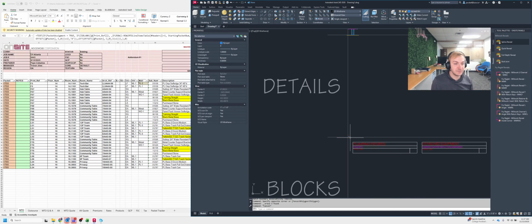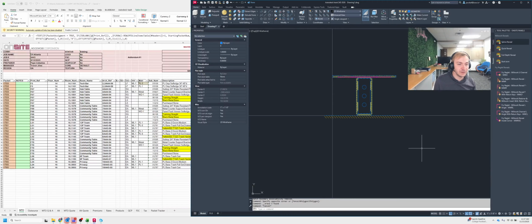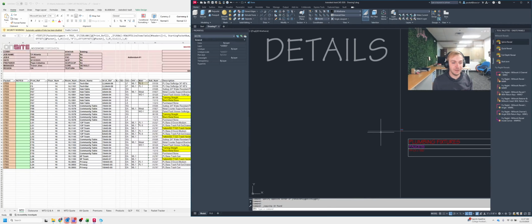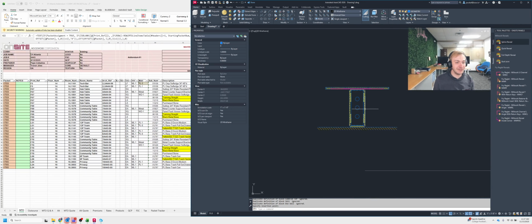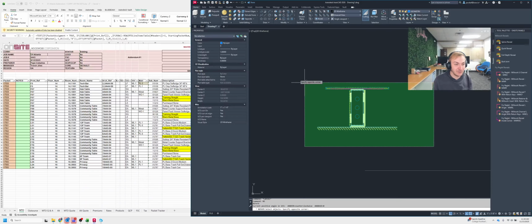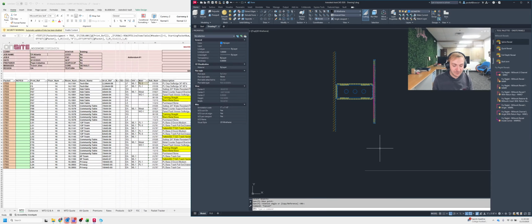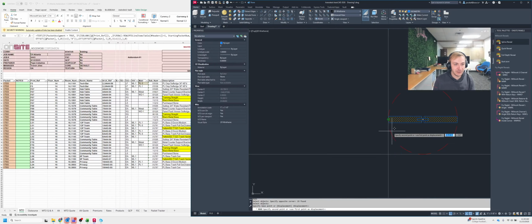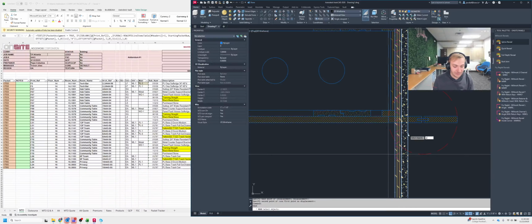So to do that, a good thing you can do is take what you've got from your section view here. We can copy that. Again, you're seeing a recurring theme here because this is something that is really going to help you out as far as making sure everything matches up. I'm going to take that section view, rotate it on its side, and then take the front of those panels and line them up with the front of the panels in the detail here.